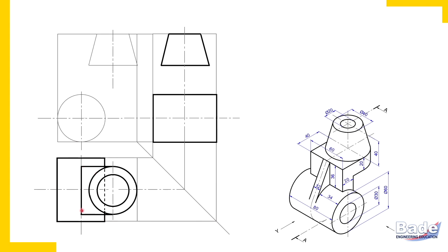And here it is, a top view of the U-shaped plate. There is overlap, but check here, the cylinder is under that U-shaped plate. So for the U-shaped plate, the overlap portion is not hidden. Try to understand. Okay. So this U-shaped plate will be drawn here as a rectangular strip of thickness 20 millimeter. Now the thickness of this plate is 20 millimeter, but it is vertical, that is the height. So measure that thickness, 20 millimeters.